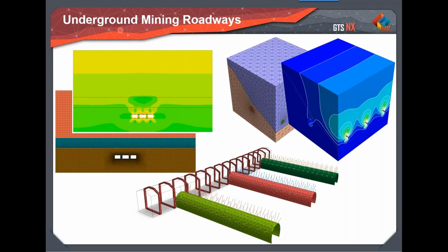And the underground mining roadways. So this is very similar to your tunnel model. You can go for the steel arches, shotcrete, or the entire segment lining, or you can go for rock bolts and so on. So all such kinds of analysis can easily be done.